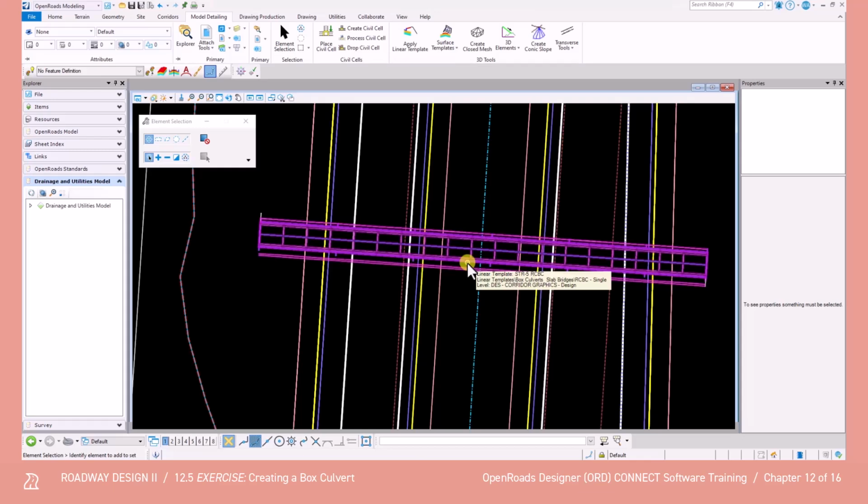So we need to know that the cell height is 8 foot, the cell width is also 8 foot, the ST or top of slab width is 9 inches, the SB or bottom of slab width is 9 inches, the WT or exterior wall width is 8 inches, and BW or out-to-out width is 9.33 inches.